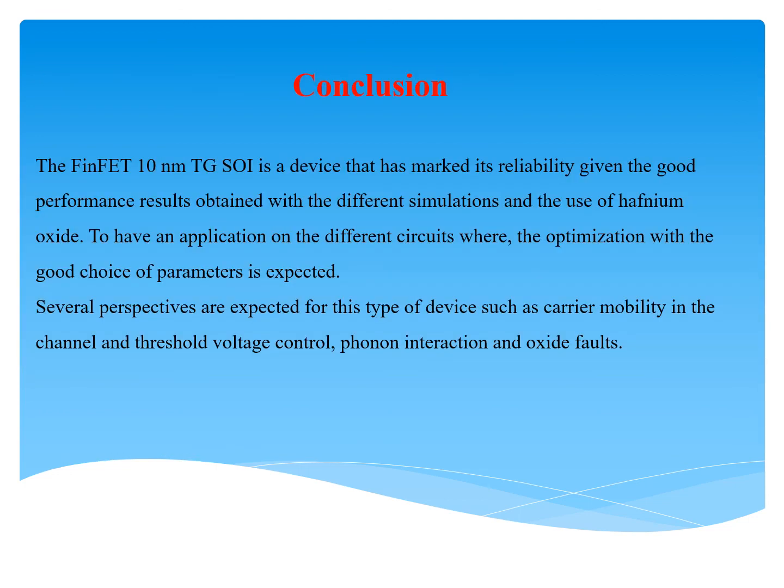Conclusion. The FinFET 10 nanometer tri-gate SOI, semiconductor on insulator, is a device that has marked its reliability given the good performance results obtained with the different simulations and the use of hafnium oxide. To have an application in different circuits, optimization with a good choice of the parameters is expected. Several perspectives are expected for this type of device, such as carrier mobility in the channel and threshold voltage control, phonon interaction and oxide faults.